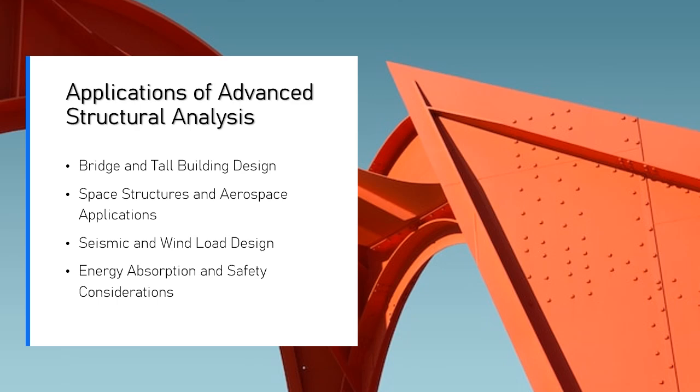Key considerations: building importance factor, higher importance for hospitals, schools, etc. Seismic design categories, SDC, range from A, low seismic risk, to F, high seismic risk. Load combinations. Seismic forces are considered in conjunction with dead, live, snow, and wind loads.